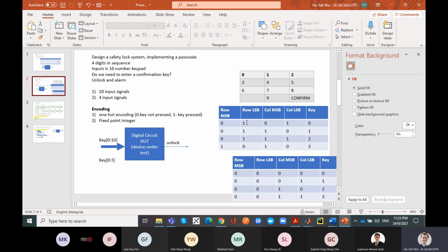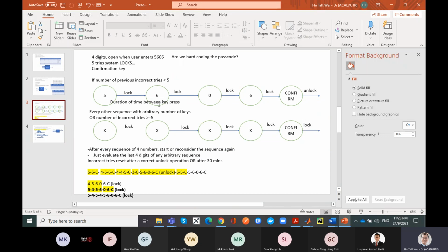Because you can see, even if you say two numbers, I have fixed point, I have 2's complement, I have 1's complement, I have floating point, IEEE 754, I got 32-bit floating point, I got 64-bit floating point. There are so many different number representations. Or if you are looking at text, you have ASCII, you have Unicode. So different bit combinations mean different things. So when you specify, you really have to define clearly what the encoding is, what every bit means, what all the patterns mean. You have to define, in response to all possible input sequences, what the output sequence is.